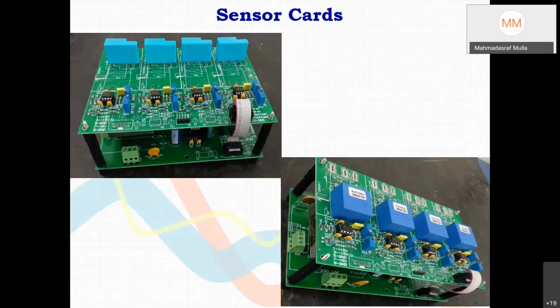So maybe 10 ampere is calibrated to 3 volt. So 3 volt whenever we are getting at ADC channel, it represents actual 10 ampere current in the circuit. And then linearly it will vary. So if you are getting 1.5 volt there, it will be 5 ampere likewise. Okay.